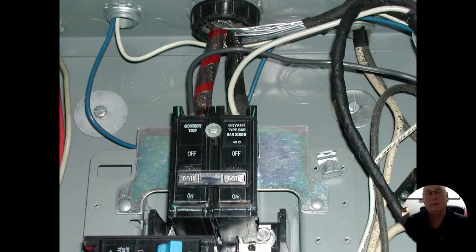This one here, I refer to this as top loading, all right? So we've got a 100 amp breaker, and the red striped wire has a single 100 amp breaker. The black wire has a 100 amp breaker that comes in there. They're tied together, all right? So even though we have two wires and each one is on a 100 amp breaker, again, we do not add these up. This is still a 100 amp service that comes in there.